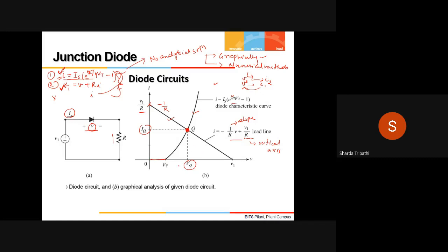What it is observed is 15, 20, 25 iterations हो जाएंगे, then you will observe that the change in current, like I at 30th iteration, I at 31st iteration and I at 32nd iteration, does not differ much. So when you see that the value of current in the successive iterations are not increasing by very large value, then you can say that, okay, one of these values is my required current, and by substituting that I in the value of voltage, you get the value of V.